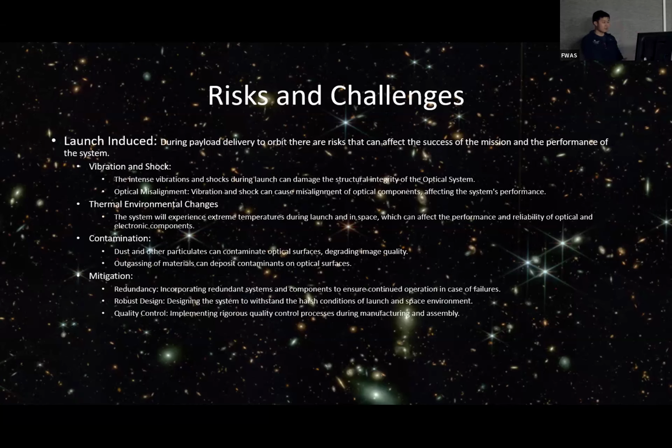Launch-induced risks and challenges: vibration and shock, right? You could talk about super high G's, more than 3 G's. Now all of a sudden you're talking about optical misalignment in your elements, and thermal environment changes from sea level all the way to the coldest space. Now you risk outgassing, which basically means the material itself lets out gas as the temperature changes. That outgassing you have to pre-plan for, to make sure none of it causes contamination of your optics.